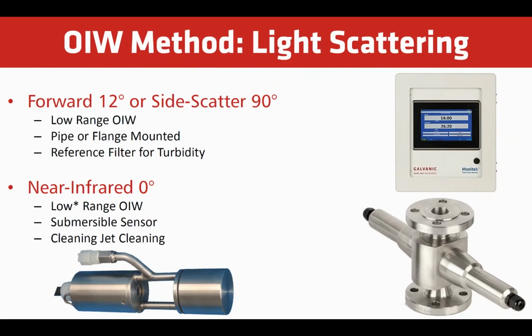Light scattering analyzers perform ratio measurements of scattered to direct light. These are ideal for low concentrations of oil and water. Installation is available for both pipe and flange mounted. These systems include a reference filter to compensate for background turbidity.